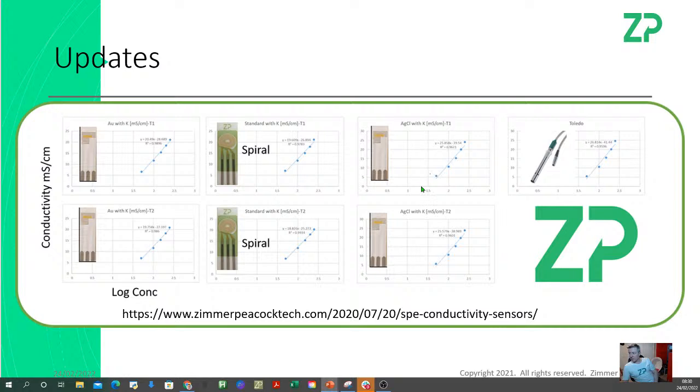And then a few years later, we ended up testing some of our other screen printed electrodes, which didn't have any fancy spiral or interdigitation, and we got exactly the same results. So there's this idea, and I get the maths and the physics of this, that the thinner interdigitated electrodes are, the smaller the gap, the better the signal. But I actually think that in reality, when you make electrodes on top of normal screen printed electrodes, you get just as good signal whether you went interdigitated, spiral, or platinum plates facing one another. They all gave us the same signal.